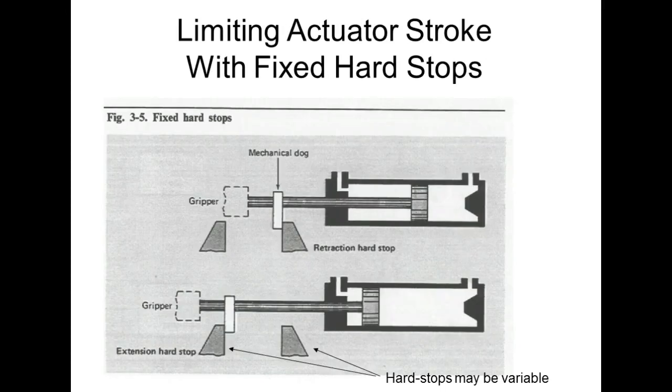Now, if we was to come in now, all of a sudden, what have we done here? We put in what we refer to as hard stops. So what have we done with our hard stops? We've limited the stroke of that. As far as the hard stop. Now, what this is, most of your linear actuators, I think all of them we got on our manufacturing lines use the actual actuator stroke.